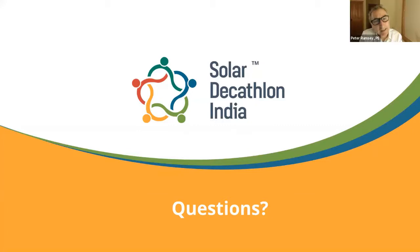Yeah, I think a quality energy simulation is a perfectly acceptable way to come up with the peak load. And in the simulation software, it does give you a cooling load requirement at every hour of the year. And so that's a very easy thing. You look at the output and you just find the maximum. Now, what I would suggest is you put a little safety factor on there.